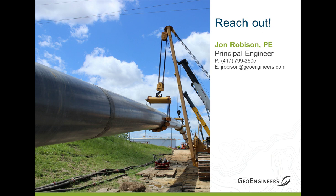And I'll also say on that subject, the tighter those specifications are, the more often that contractor is going to have to get in and out of the pipe to survey the location and confirm and recalibrate the system in order to hit those very tight tolerances. So when you need a really tight tolerance, expect to have slower production and expect to pay more. But if you don't need it, then in my opinion, there's no reason to do anything more than say 2 feet, if you don't need that tight tolerance.